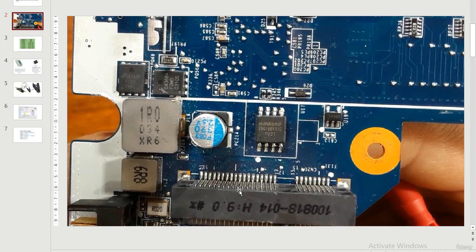You check the connectors, you find that all the connectors are not damaged. All voltages are present, but the problem is still here. The motherboard is dead, which means 100% you should reprogram the BIOS. You have a corrupted file inside the BIOS.